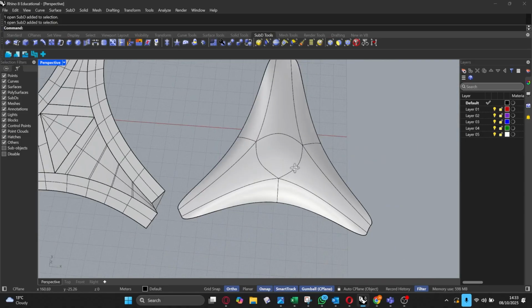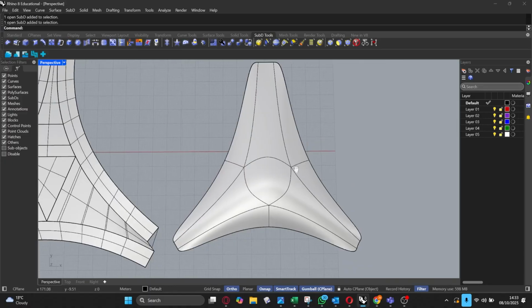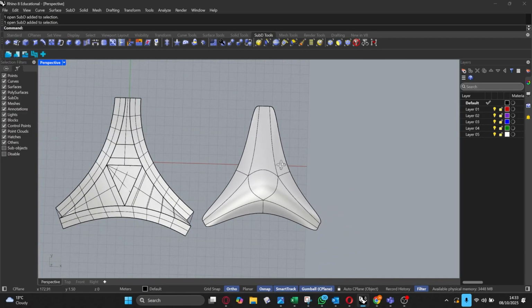Okay. Now, one of the rules that I'm going to teach you, which is really critical for SubD modeling, is a rule that applies whether you're SubD modeling in Rhino, in Maya, or in Blender. This rule is always the same, and it derives from the gaming industry and the animation and entertainment industry, which tell us to typically work with quads. Okay, so what is a quad?